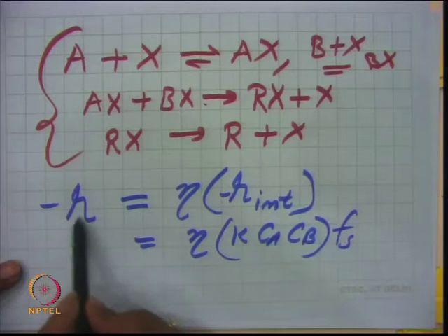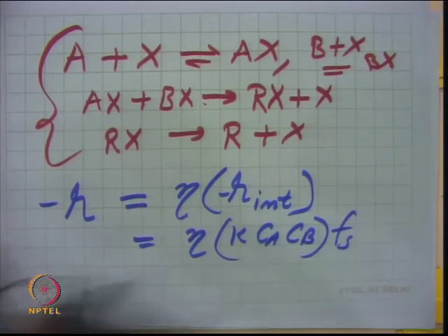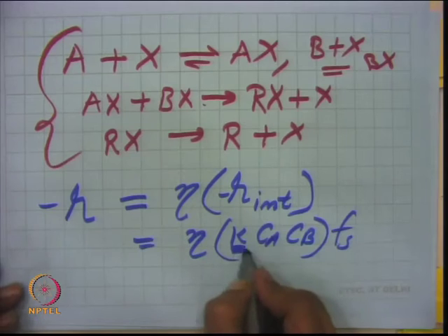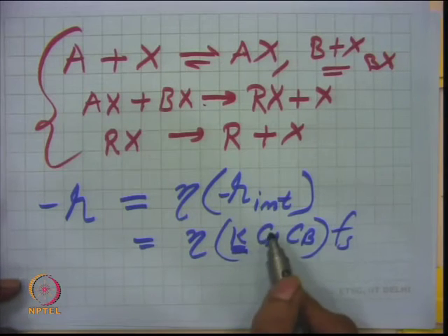So, the fraction of the catalyst or solid in the bed, or one can write it in terms of the mass or concentration of the catalyst, mass per unit volume, especially when you have a slurry bubble column reactor, where catalyst concentration is also important. The mass of the catalyst will come here because we are calculating the total rate of reaction, or total moles transported. The choice of per unit volume or per unit mass fraction of the catalyst is yours, decided by the unit of the small k written here.